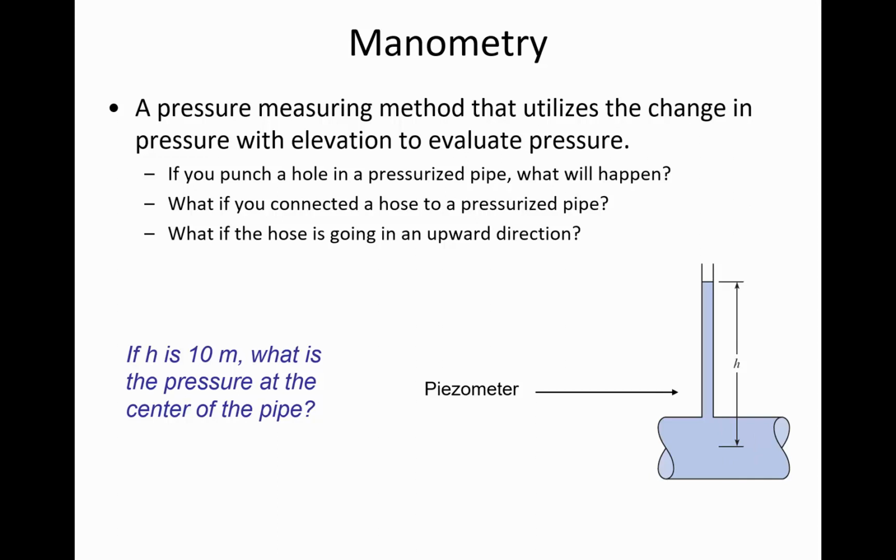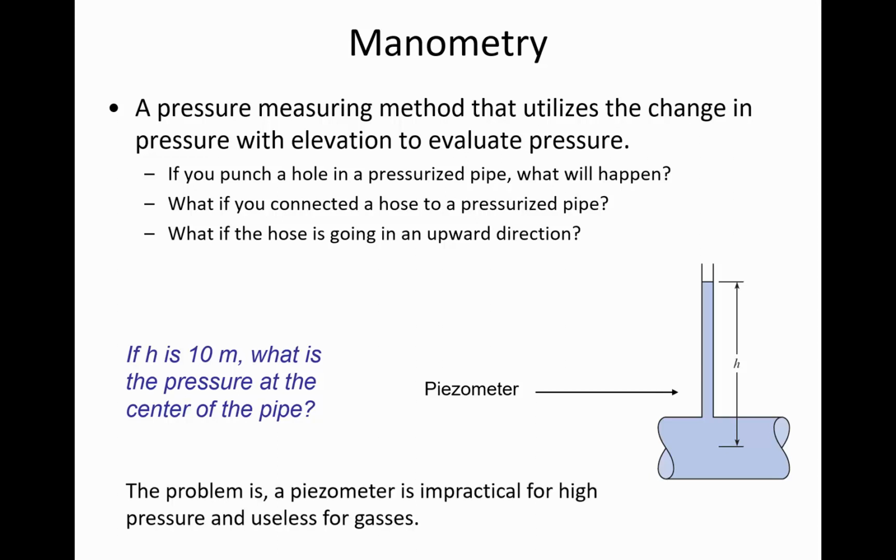And so it's important for us to know what piezometers are, and we're going to use these in the lab later in the semester. We will use piezometers in order to measure the pressure inside of the venturi. When we do the Bernoulli lab, then we're going to actually see the pressure change through the throat of a venturi, and we're going to measure the magnitude of that pressure change with a piezometer, very similar to this. But it's just one of the simplest ways for us to quantify pressure change.